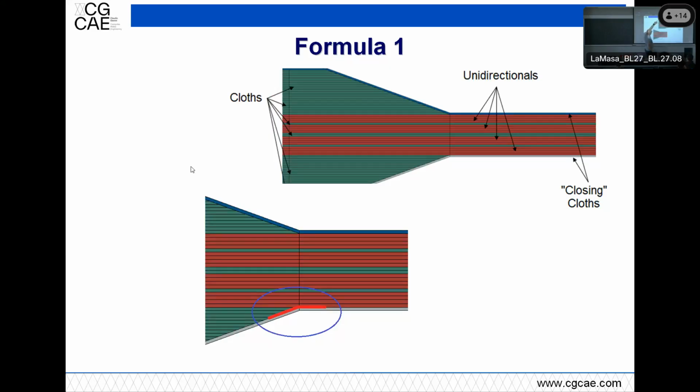So this is the thick part, which is then bolted to the monocoque, and this is the flexure. There are a lot of UDs, unidirectional, so stiff, and some cloths inside, plus closing plies to protect all these, which would otherwise end up visible and easy to scratch.